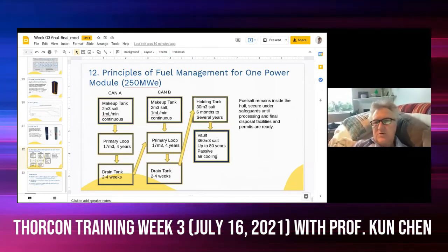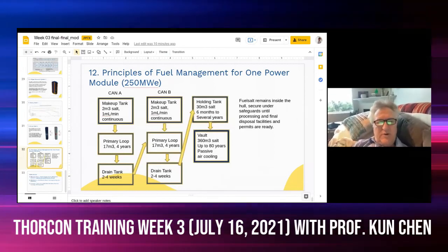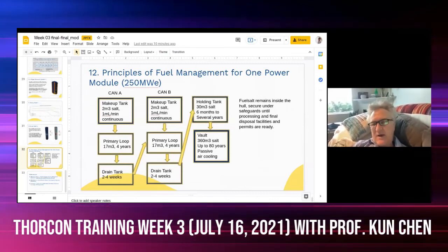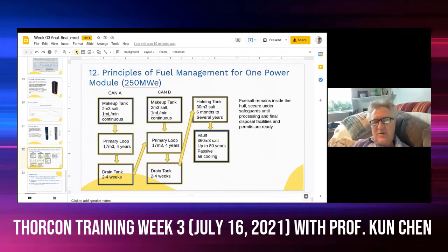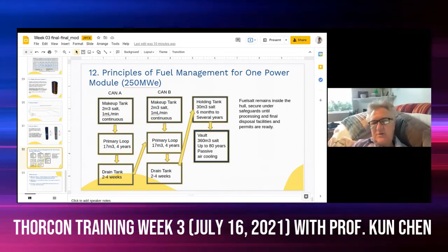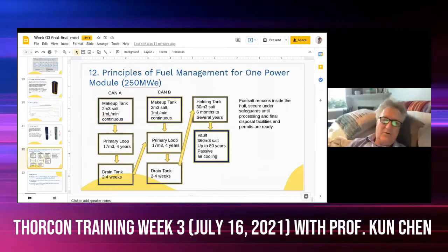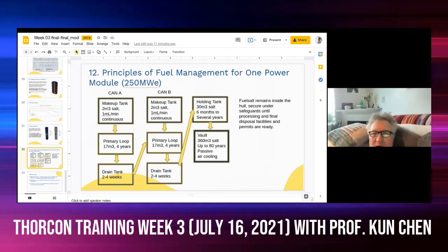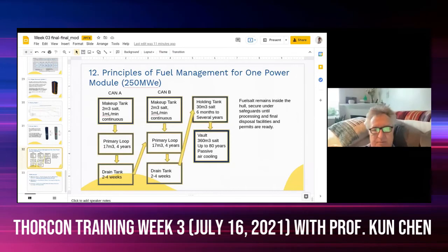Here we're closed loop. So we can measure the temperature and say, we're a little bit hot, so let's add less makeup salt. Or it's a little bit cold, the reactivity is a little bit low, we want to add more makeup salt. So you can continuously adjust how much makeup salt you're adding. That can compensate a lot for uncertainties in the design.